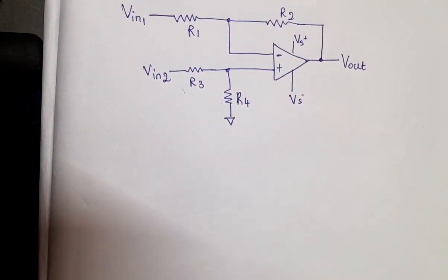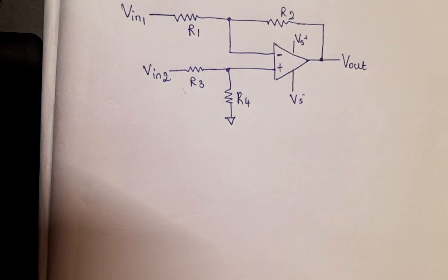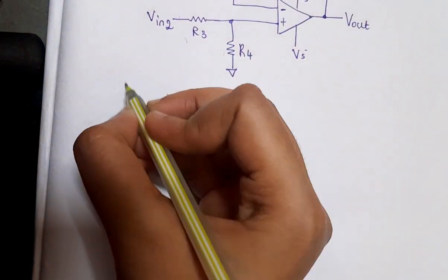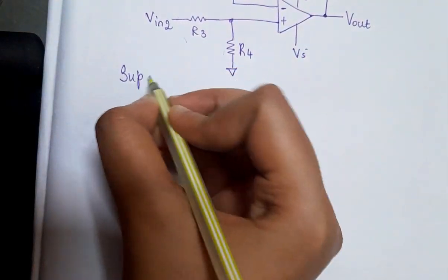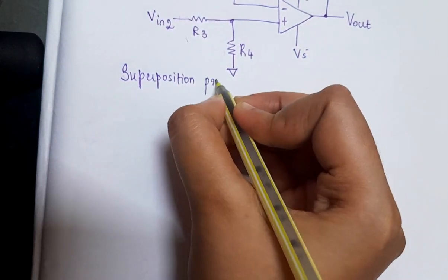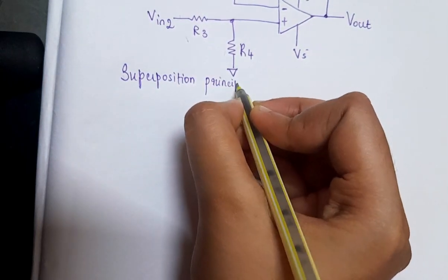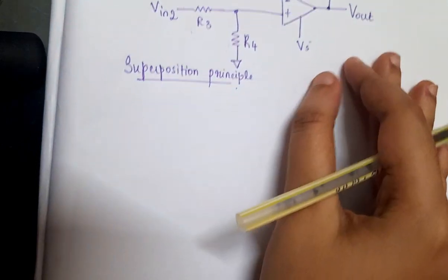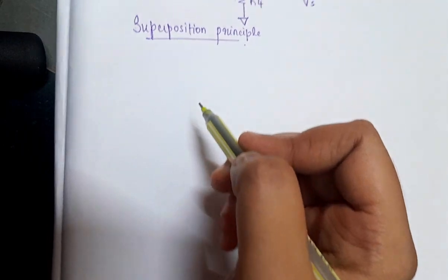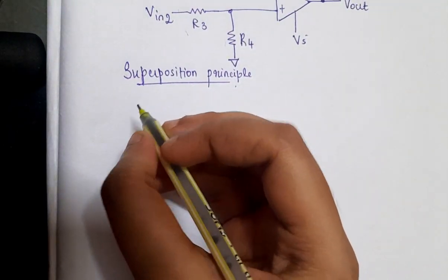We can analyze this circuit and find the Vout value by using Ohm's law, Kirchhoff's law, and also the voltage divider rule can be applied. Let us analyze the circuit. We can use the superposition principle as two voltage sources are involved, Vin1 and Vin2, which can be separately analyzed by considering one voltage input at each time.